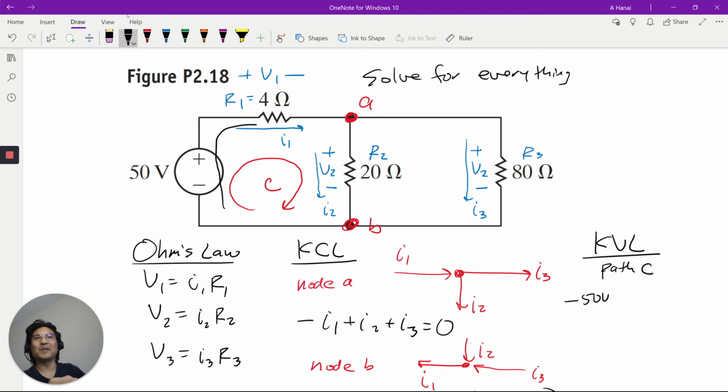Okay, now we're going this way. So look, this way, right? That's positive V1. Going this way. This now going down this way. So that's positive V2. Equals 0. That's KVL. So that's an independent equation. Now we have 5 equations. 5 independent equations. For 5 unknowns.